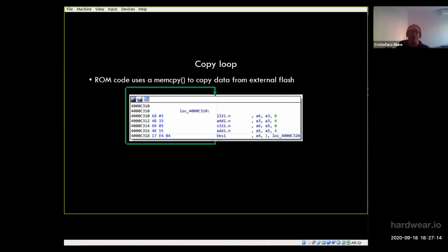But there is one very important point here: in Xtensa, like in many other architectures, you don't have an instruction that, if modified, is going to load directly into PC. You cannot address PC directly. There is no instruction like that. ARM is quite peculiar in this part, ARM32 actually, where you can use PC as a destination register. This is quite an interesting design choice, but this is not available in Xtensa.